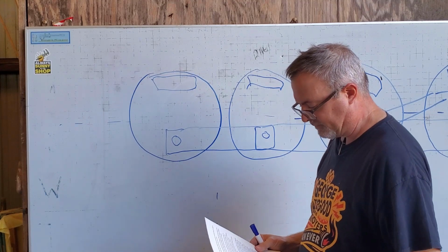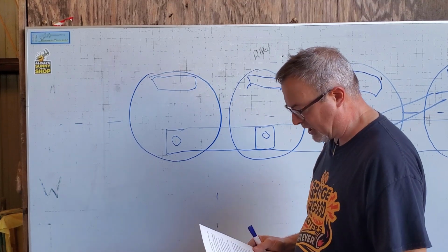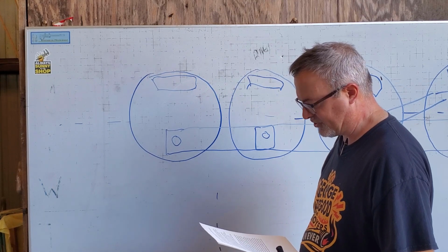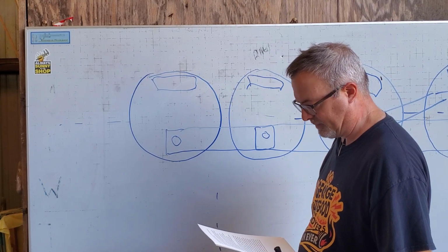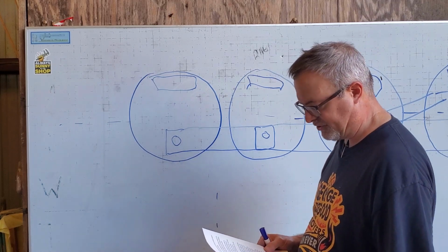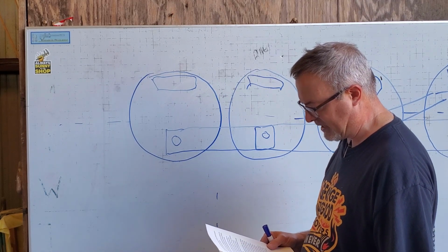Number 12, the flywheel size and mass can affect the governor operation, since a flywheel with too much mass may slow down the reaction of the engine to changes made by the governor. This is my understanding of it anyway. Reading books only gets you so far, though. Nothing like having an engine to try things with.